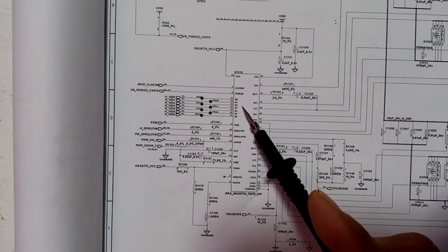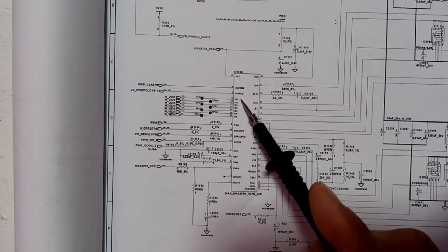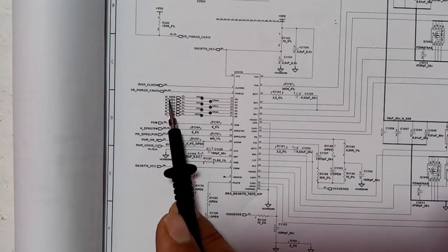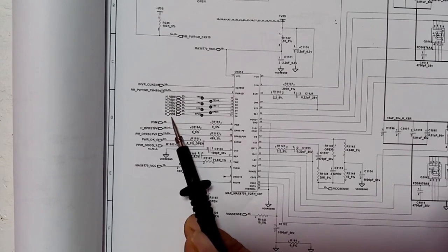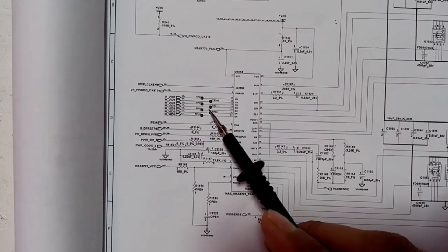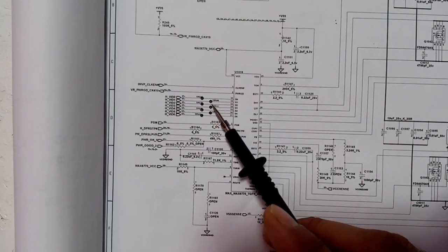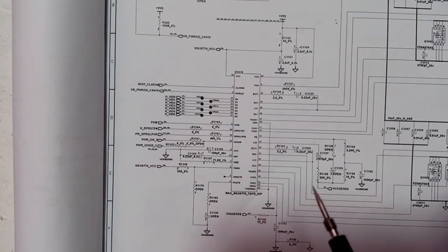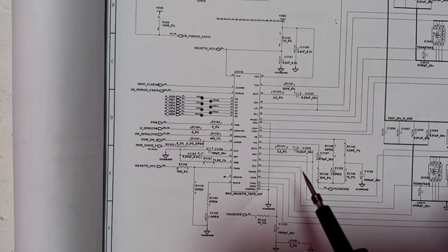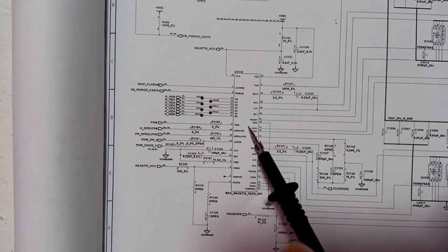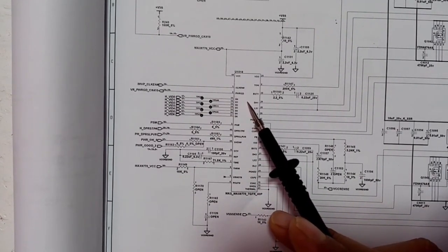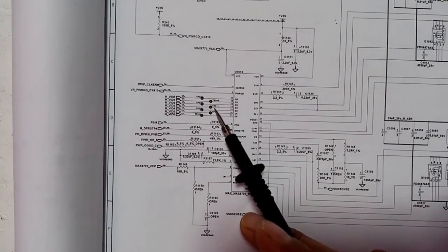And over here, we have the ID signals. We have here 7 IDs. As you can see, we have voltage ID 0 till voltage ID 6. So basically these signals have the purpose of determining the appropriate voltage for this CPU. Every CPU has its specific IDs. Based on these IDs, the IC can know the exact VCC core that should be generated. That's why we have these IDs.